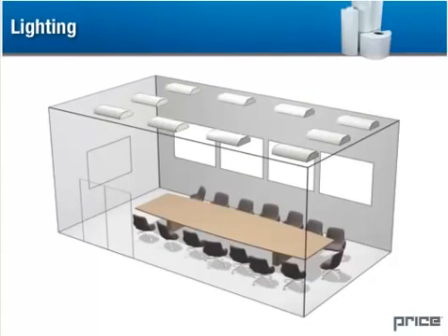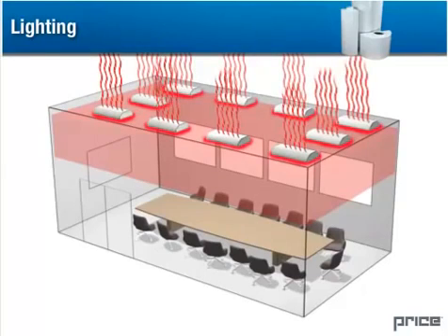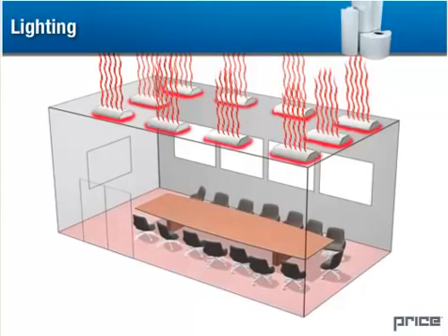It's easy to see how overhead lights contribute the majority of their load to the upper zone. A light fixture has a thermal plume, but because it's already in the upper zone, all of the convective loads will be in the upper zone. The radiative component of the lighting load will put a smaller load in the occupied zone as heat is transferred to all surfaces in this space.